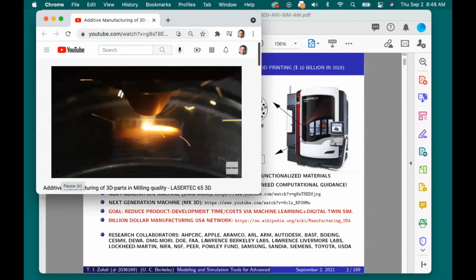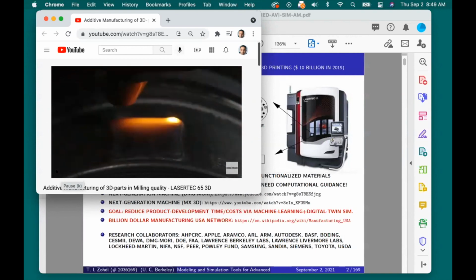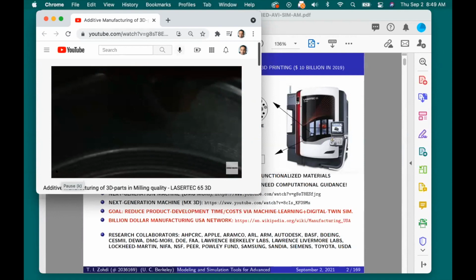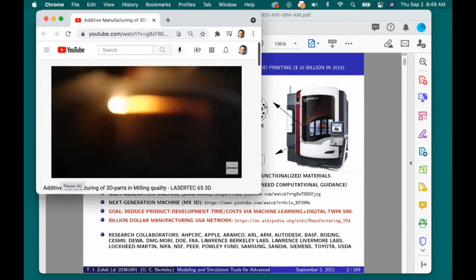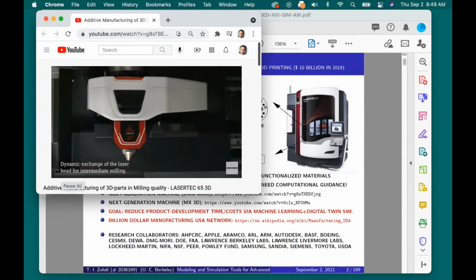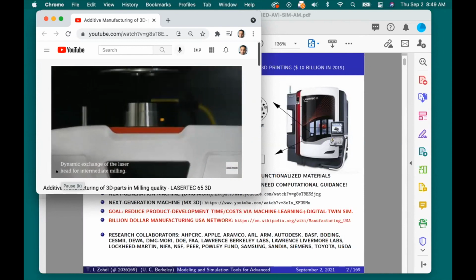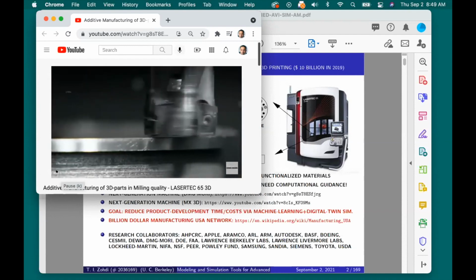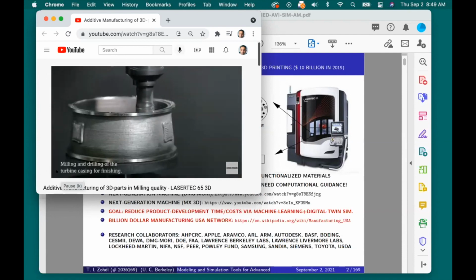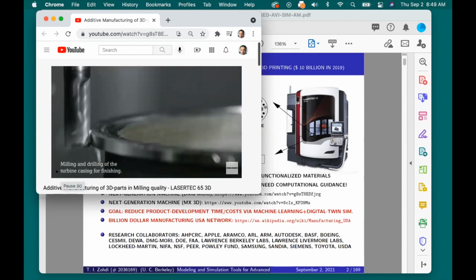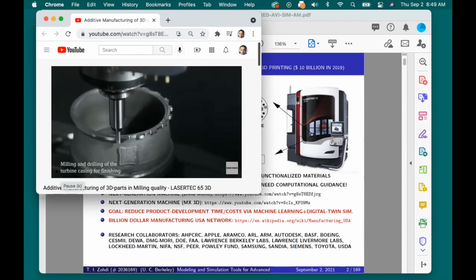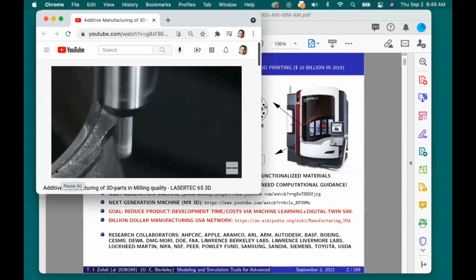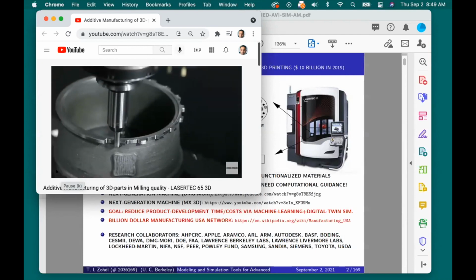So as a solution or partial solution, this machine also does the subtractive part, because additive manufacturing by itself is hopeless. I mean, we really know that in reality. It also has to have subtractive capabilities for machine tolerances. So this gadget takes a subtractive milling device and starts to clean up the mess that the additive manufacturing made. And of course, then it goes through a complicated series of adding and subtracting. And you can imagine this machine is not the easiest to manipulate.